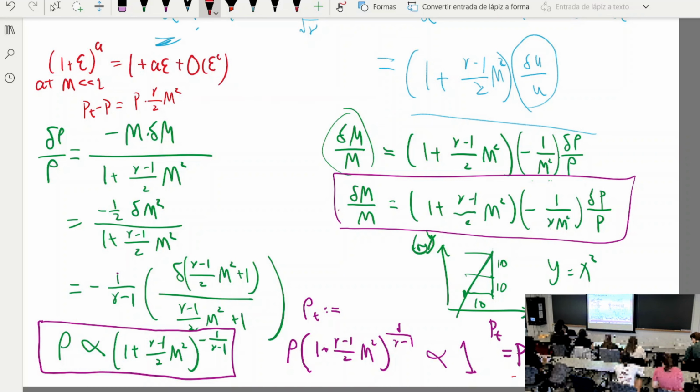Okay? And M squared by the definition is going to be u squared divided by gamma p over rho, right? So I have gamma over 2 here. And the gamma cancels out, p cancels out, I get half of rho u squared, right? So that's the same as our incompressible relationship of how stagnation pressure is equal to the static pressure plus half rho u squared. That's basically Bernoulli's, right?